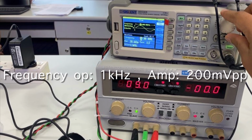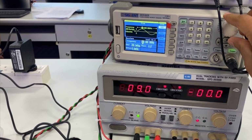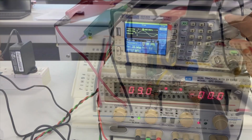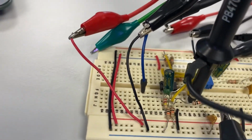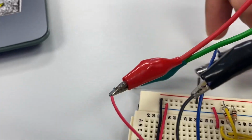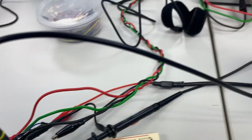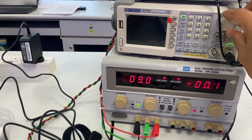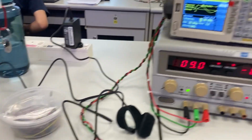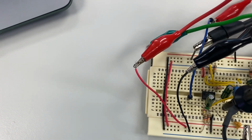First of all, we will set the function gen to a sine wave at 1 kHz frequency output and amplitude set at 200 mV peak to peak. Next, we will connect the power supply lines to a DC supply voltage of 9. Next, we will connect the function gen to test point 1 using this blue wire. We will connect the other clip of the function gen to ground.